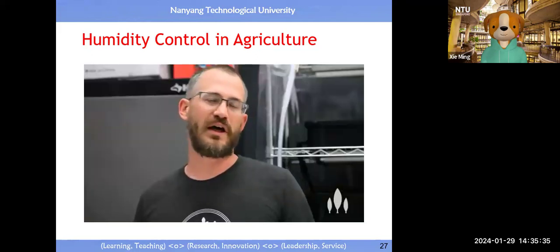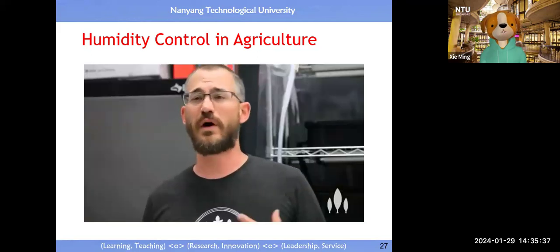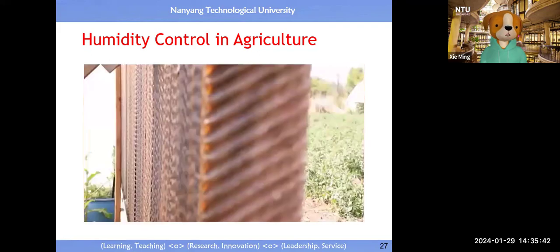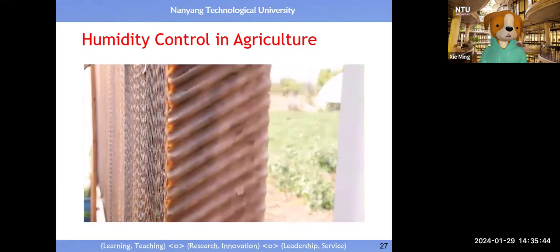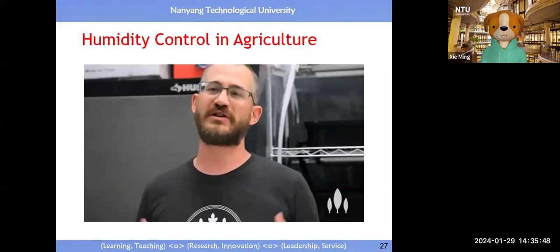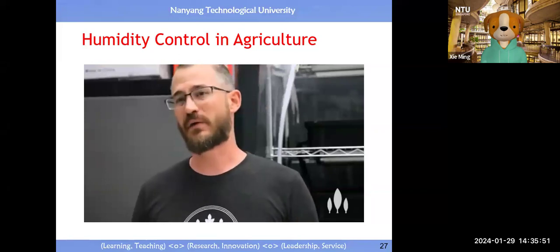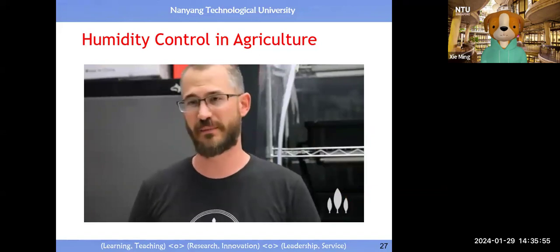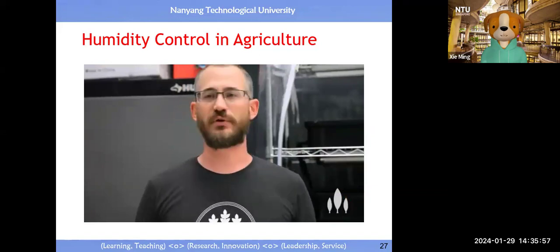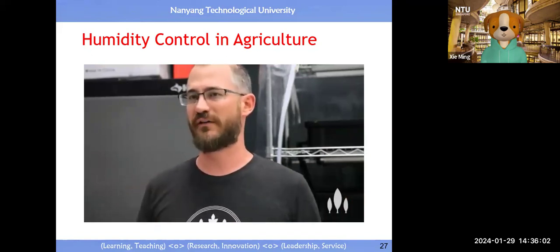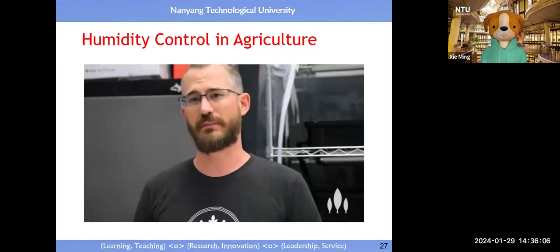A lot of folks ask about cooling walls. Well, cooling walls and swamp coolers work in really dry environments because they're dumping water vapor into the air, which means they're actually adding humidity to the air. That's typically why they're not very effective at high humidity levels and why they work so well in dry environments. If you're growing in a greenhouse that uses the cool wall effectively, you probably don't have a humidity problem because you're already in a place with really low humidity.